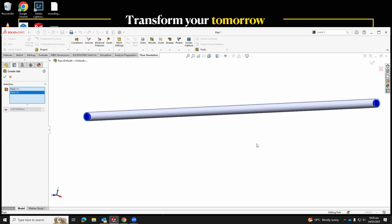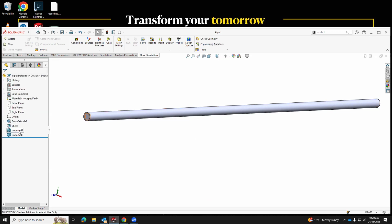And these lids are very important to set up our boundary conditions. Without them, my boundary conditions will not work for internal flows. So you see face 1 created, face 2 created, and I click on OK. You see by default here is created for me imported and imported. I created 2 lids by default. Okay.